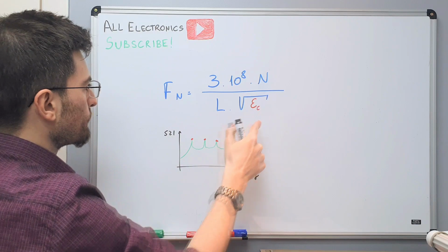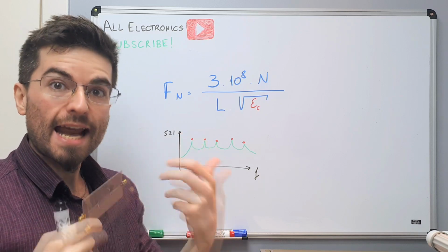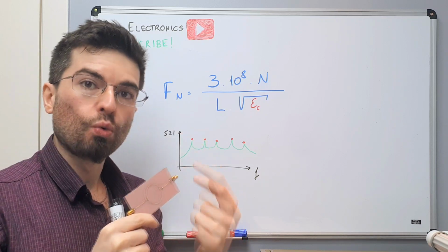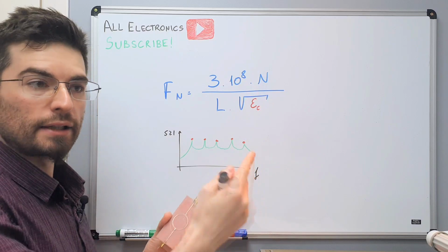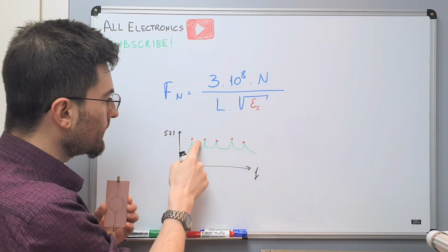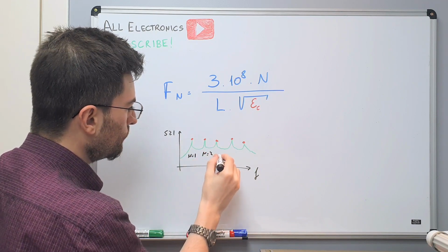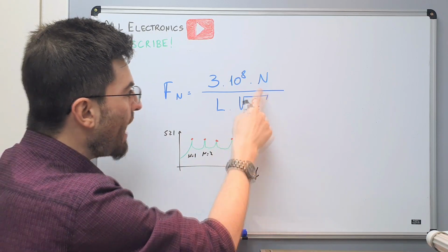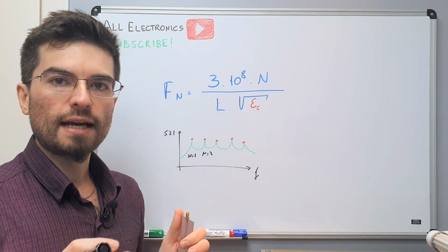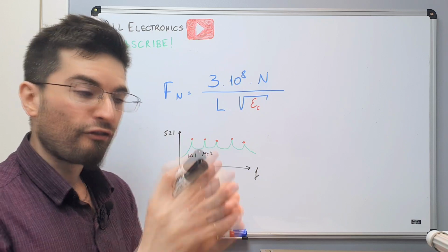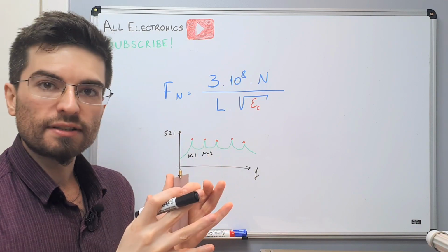This is the equation, guys, for the resonant frequency of the ring resonator, or actually any resonator that's resonating at one wavelength, based on the harmonic number, like the fundamental, this peak here, or the next harmonics. This is n equals 1, n equals 2, right? And here we have the effective permittivity, or the effective dielectric constant. This is very important, and I will explain the difference between the effective dielectric constant and the dielectric constant of the material. But let's first try to understand this equation.